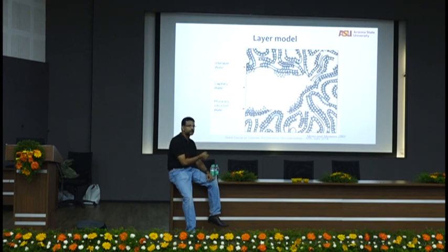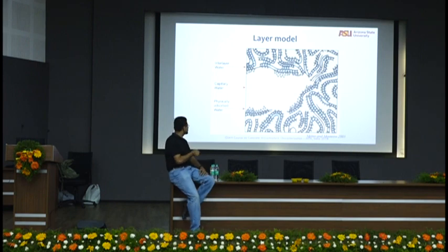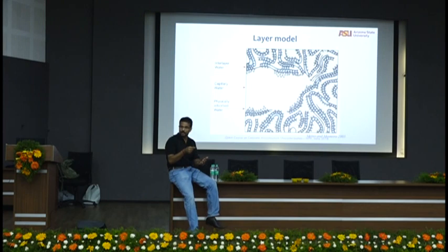You remember that number? You should remember that number. 0.23. 23 grams of water in 100 grams of cement is your non-evaporable water if all the cement has hydrated. Now, if I burn this sample from 100 degrees Celsius to 1000 degrees Celsius, I am removing all this water, right? So, you know how much is the mass loss.